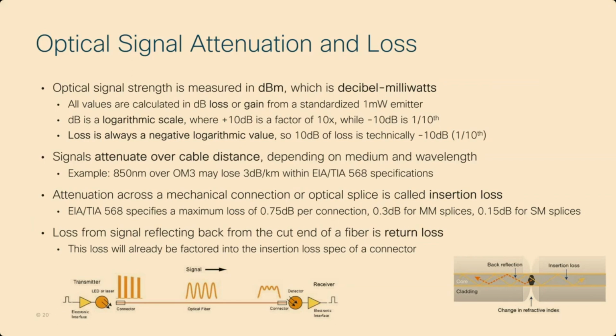So if you are looking at a cable and the spec of the cable says that the loss for the distance of that cable is, let's say, minus 2 decibels, then you're going to know that the return loss is actually accounted for in the spec for that cable. So you don't need to count that, but you do need to count for insertion loss.